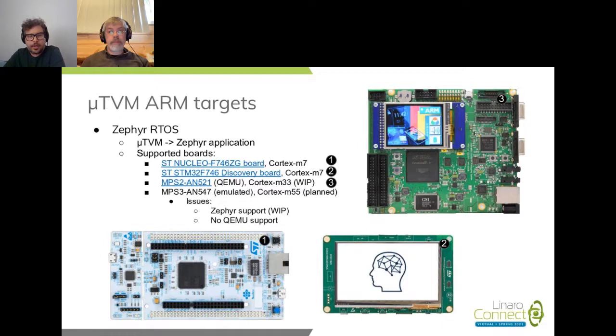There is current work from the embedded folks at Linaro to enable Zephyr to run on the MPS3. There was a pull request for that, but we don't have support in QEMU. However, there is the FVP from ARM, which is the Fixed Virtual Platform, the emulator from ARM, which one can use instead of QEMU to run and experiment with µTVM on top of MPS3 boards.